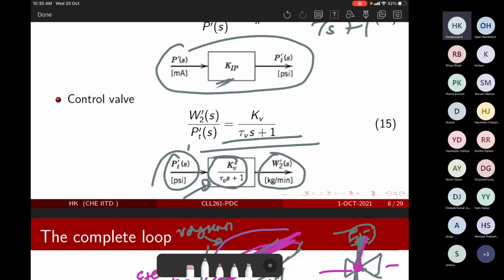what you would do is supply air line and keep your control valve in line, and this you most likely will do in your process control lab next time. So you would take a scale, then you go back and see. So you would supply 3 psi pressure and check what is the stem length.